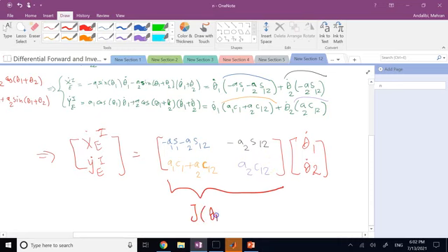So in general, with that Q notation, J is a function of vector Q, okay? So it's not constant. It changes from point to point as the robot moves, theta 1 and theta 2 change. But clearly, the components here do not depend on the velocities. Okay, so that is your Jacobian.